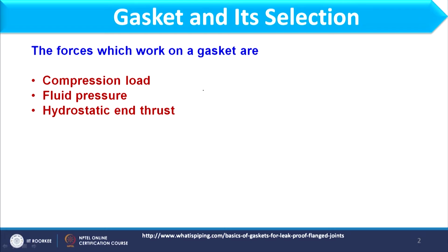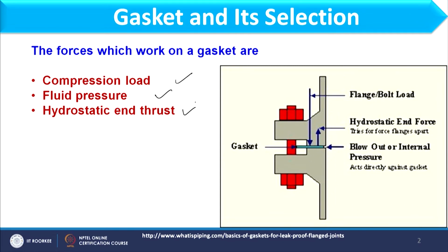So, let us start with the design of gasket. First of all we will discuss what are the forces which are acting on the gasket, because only then we can choose the correct material. Here you see I am having different forces which work on the gasket, that is compression load, fluid pressure and hydrostatic end thrust. That can be easily understood by this image.